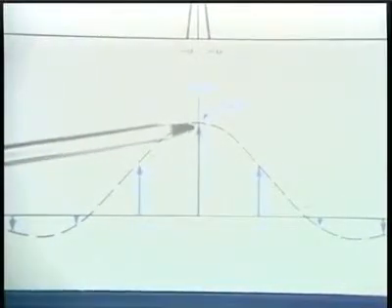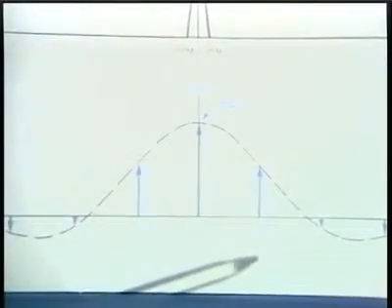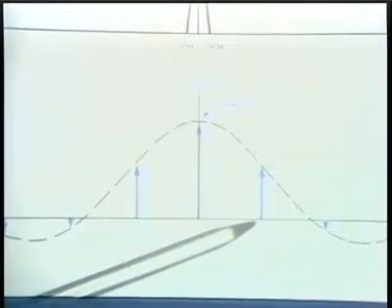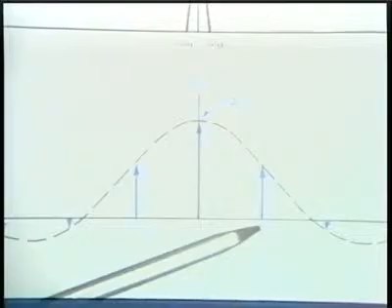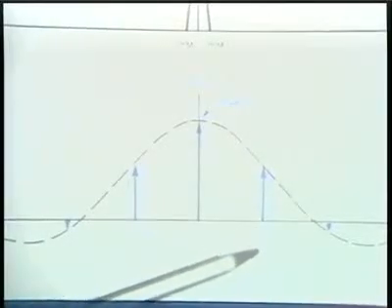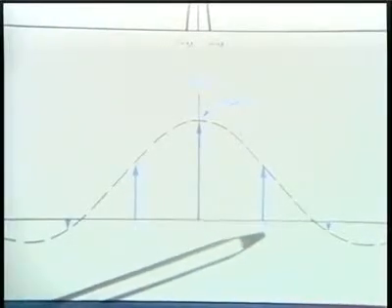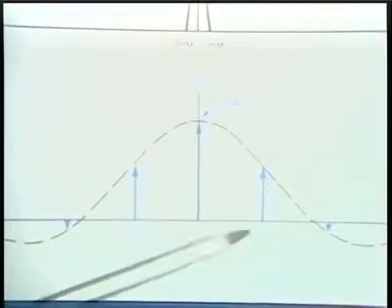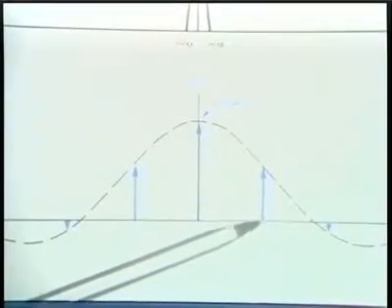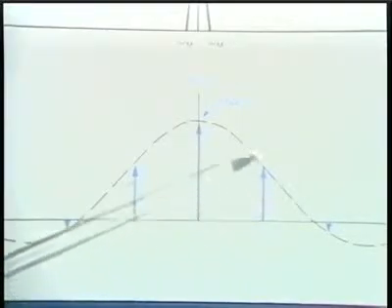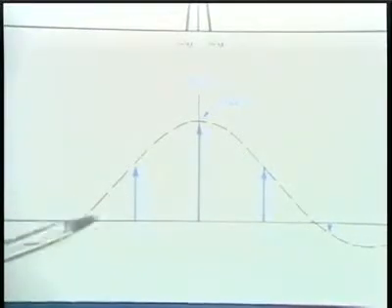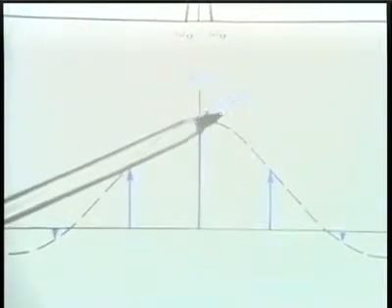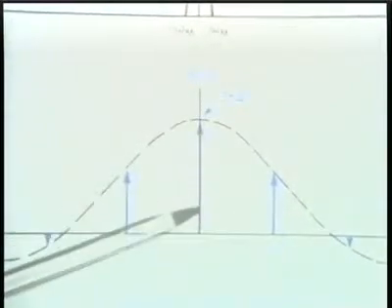The Fourier transform is impulses, and the spacing of the impulses is associated with the fundamental frequency of the pulse train, and that's omega sub p. So omega sub p is 2 pi divided by the period of the pulse train. And the amplitude and shape of this envelope is dictated by the parameter delta, which has to do with how wide the pulses are.